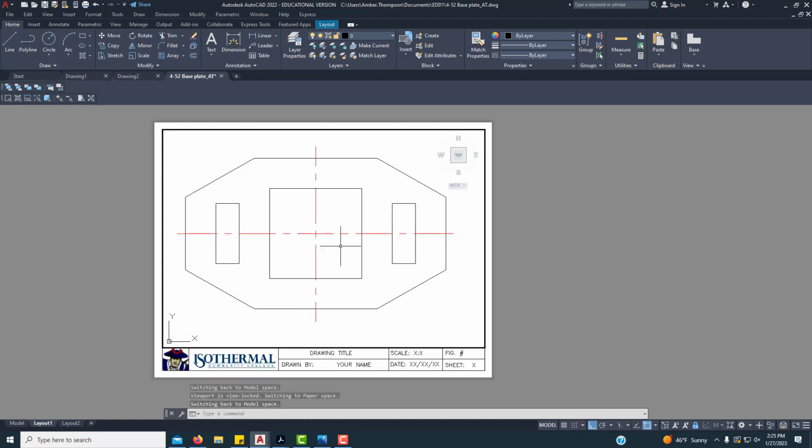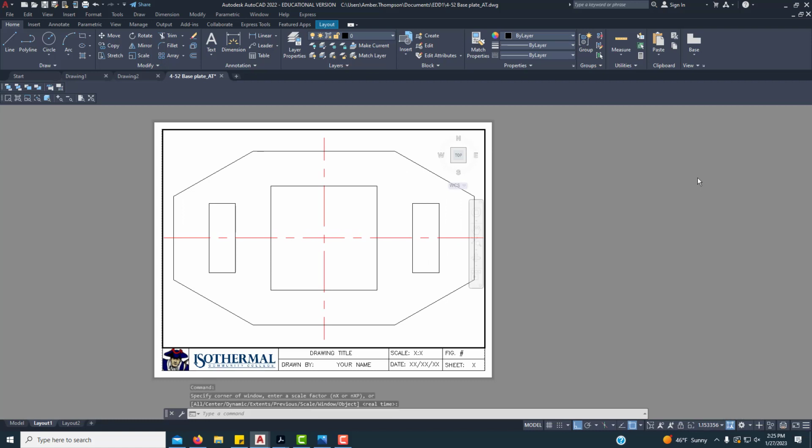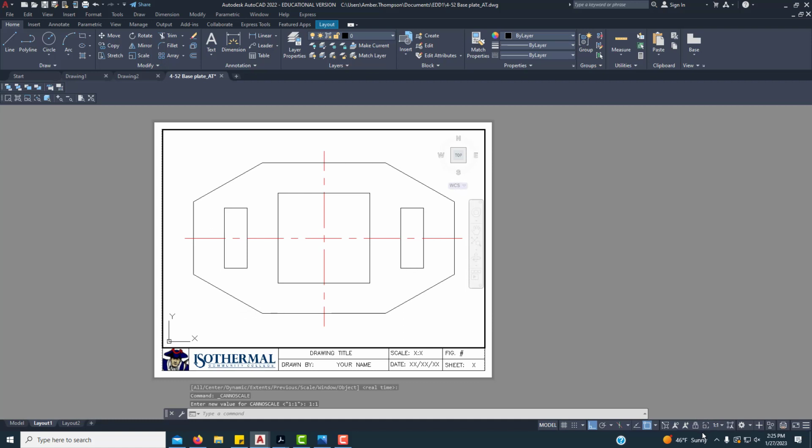And then if I try to zoom, it will not change the size of my object in perspective to me. It just zooms all the way, the whole paper zooms. You'll notice that it's not centered up as much anymore. What I did when I zoomed in and out, I put it off center. So I'm going to unlock it, hit zoom extents, change my scale back to 1:1, and then lock it back. And that keeps it right in the center of my viewport in my drawing.